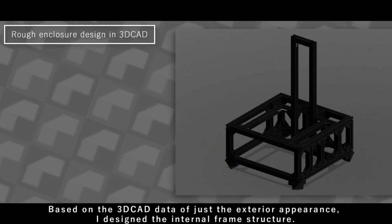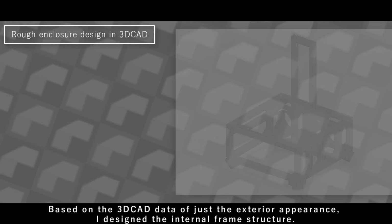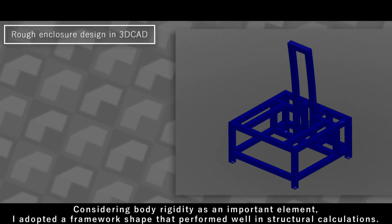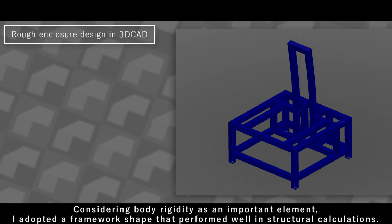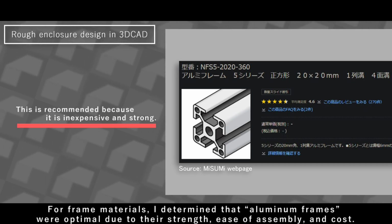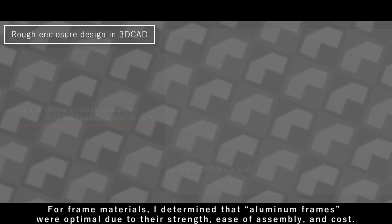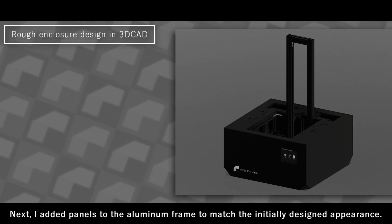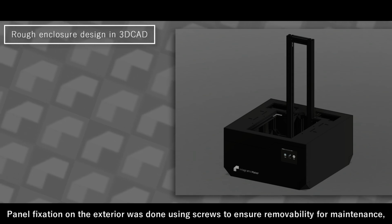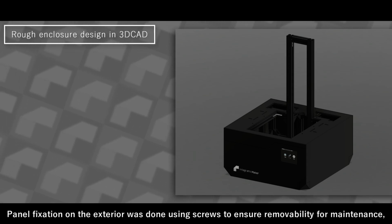Based on the 3D CAD data of just the exterior appearance, I designed the internal frame structure. Considering body rigidity as an important element, I adopted a framework shape that performed well in structural calculations. For frame materials, I determined that aluminum frames were optimal due to their strength, ease of assembly, and cost. Next, I added panels to the aluminum frame to match the initially designed appearance. Panel fixation on the exterior was done using screws to ensure removability for maintenance.